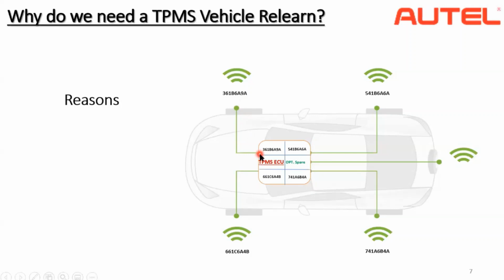So the stored values will still be for the situation where the tires have not been rotated. That's why certain procedures, or TPMS service, has to be carried out while doing a tire rotation and various other conditions. I hope that is clear.